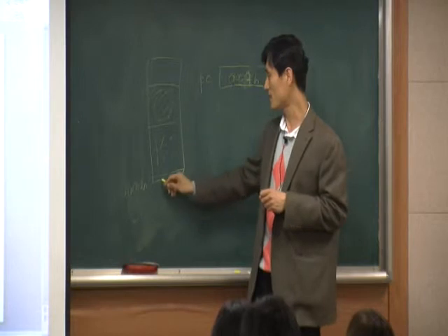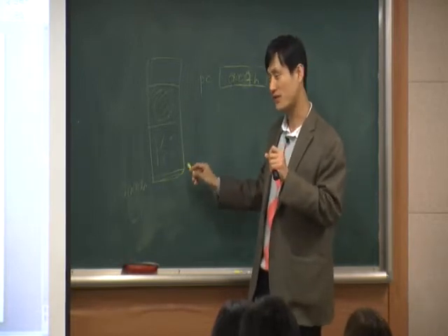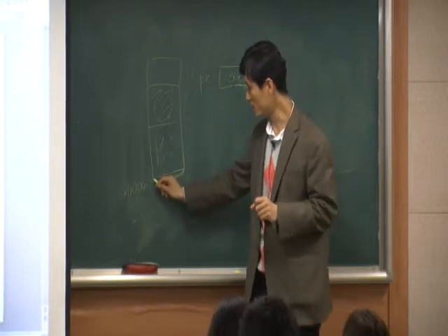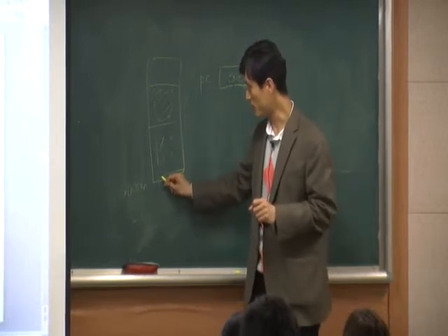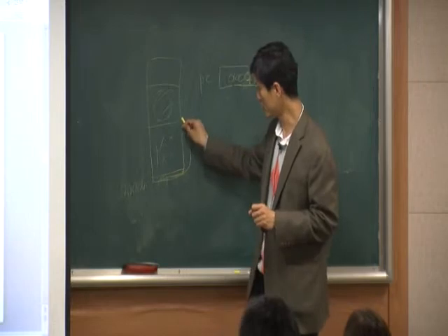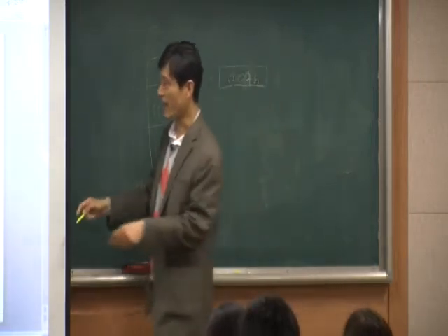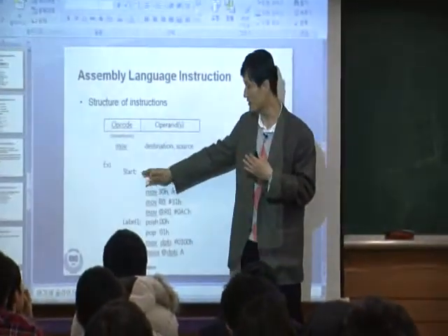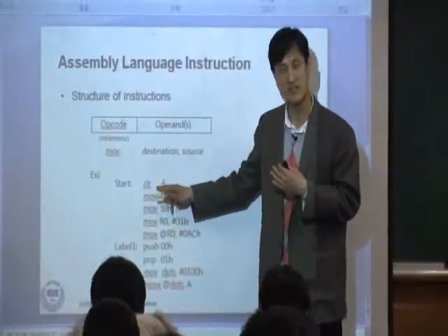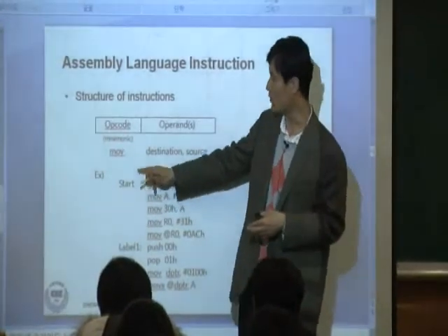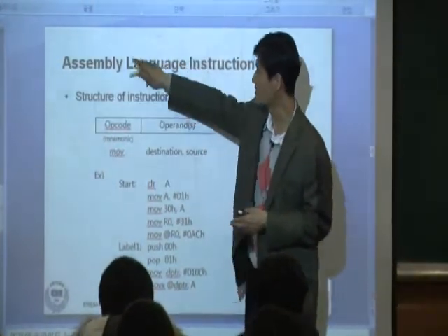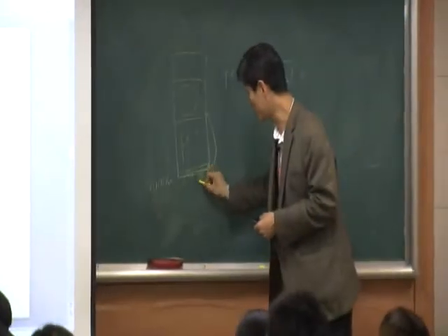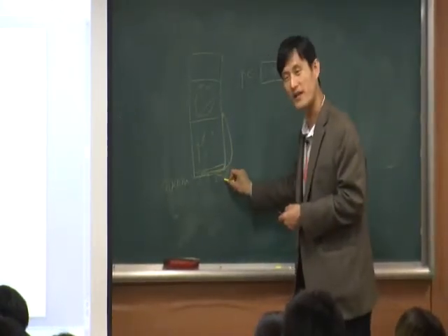So what happens is that for every microprocessor, in your assembly code, what you have to do is, at 0000H, you have to say jump. Jump to this place. And that's why I put the label start. This is my program. I have to put the label start at the first line. Why? Because I want to do jump start at 0000. Okay? At 0000, I have to put jump start. And start is my label.